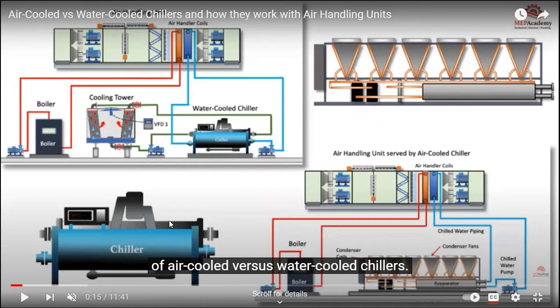Important things. The water-cooled chiller is something that is in the basement. The cooling tower, or refrigeration tower, is on the roof. And these air-cooled chillers are always on the roof. Okay. So this system is more complicated, probably more efficient, but in terms of architectural design it's more complicated, because we have part of the system in the basement and the other part on the roof. Here, everything is in the same box, and they are always on the roof.